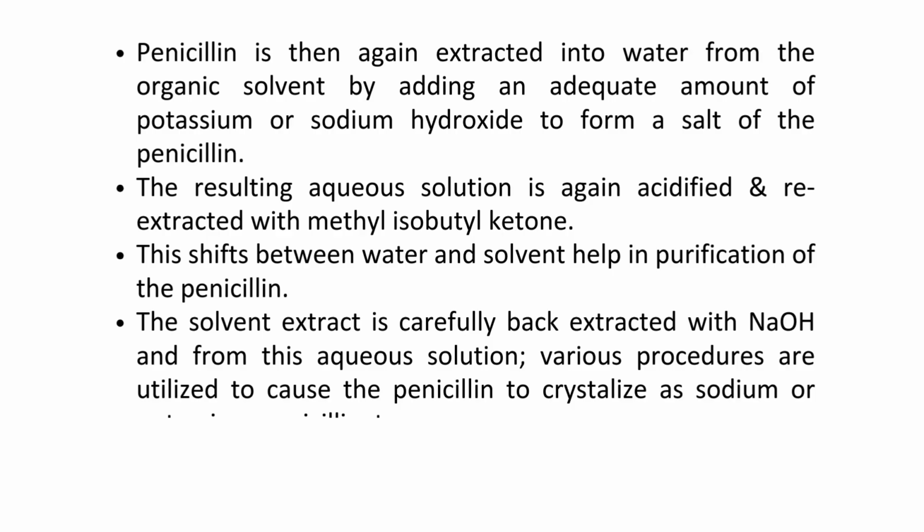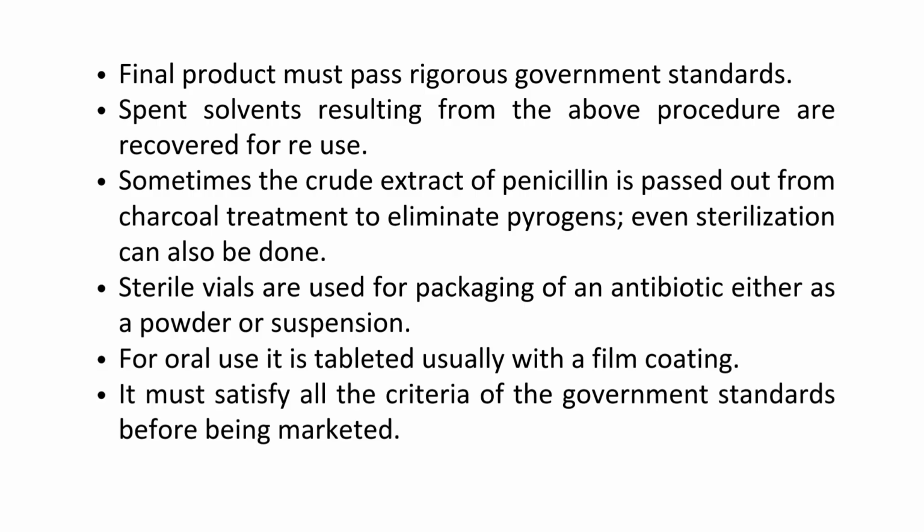The solvent extract is carefully back extracted with sodium hydroxide, and from this aqueous solution, various procedures cause the penicillin to crystallize as sodium or potassium penicillinate. The resulting crystalline salts are then washed and dried. Finally, the final product must pass rigorous government standards. Spent solvents from the process are recovered for reuse.